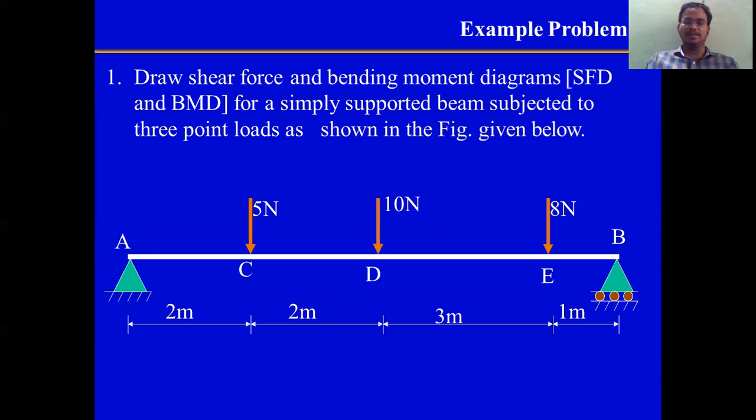We will see one problem directly. We will enter into an example problem. Draw the shear force and bending moment diagrams, SFD and BMD, for a simply supported beam subjected to three point loads as shown in the figure given below.